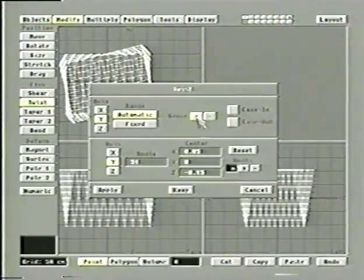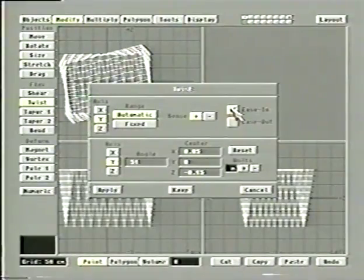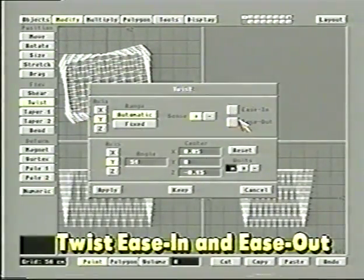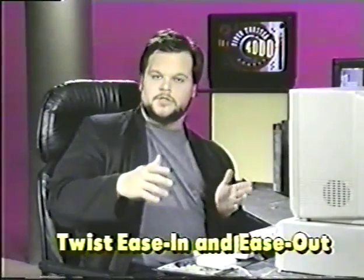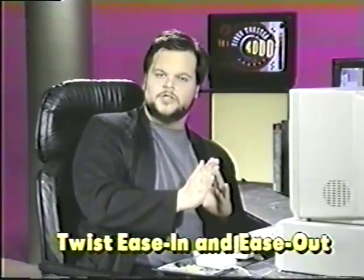Finally, let me just mention, since we're in this requester, for purposes of completeness here, ease in or ease out. What this does, instead of just twisting the whole thing at a uniform rate, it starts the twist a little bit slower if you have ease in, and then it picks it up. So it sort of gives you more of a gentle beginning, and then it moves a little harsher at the end. Ease out means it's gentler at the end, and a little harsher in the middle. And this, again, is just a way of creating sort of a smoothing effect as you start to go into these functions. And you'll notice the numeric requesters for all of these.